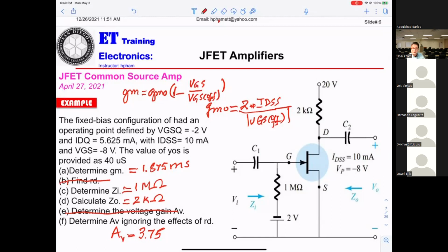Like, if you want to amplify the signal, you can use a bipolar or JFET amplifier. If you want the input and output to be opposite for the JFET, then you have to use common source. Don't think too far away from that. That's the minimum thing you need to know.